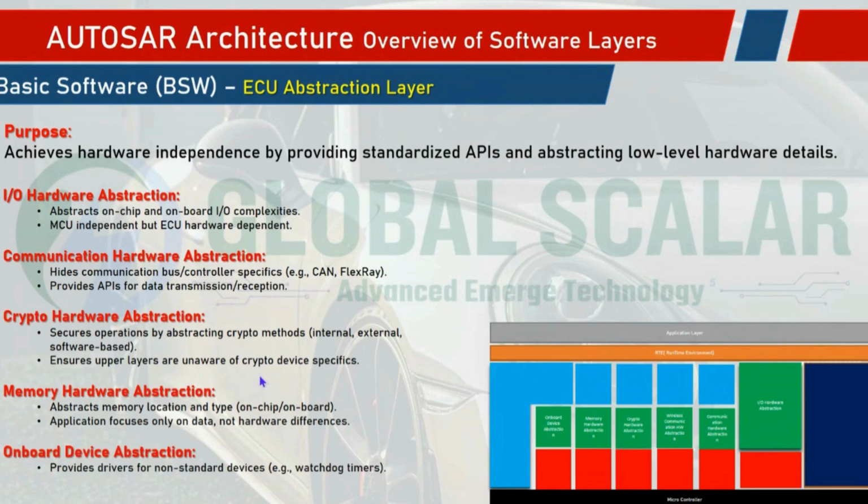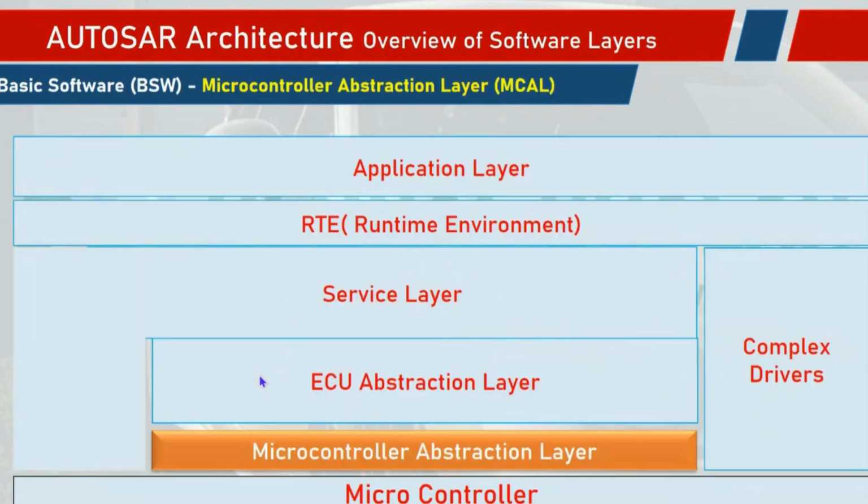Onboard device abstraction provides the drivers for non-standard devices such as the watchdog timer, and we need to ensure consistent interfacing of the data transmission across the different modules. So these are the ECU abstraction layer components. And next will be a part of the MCAL.